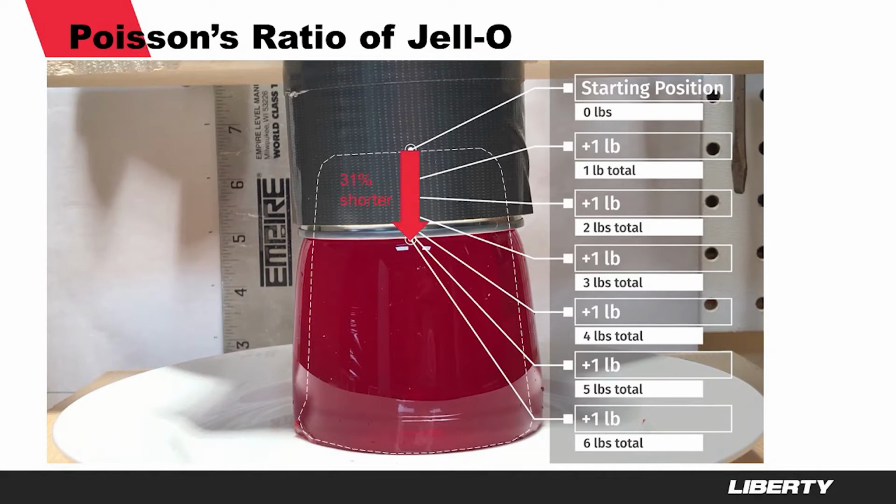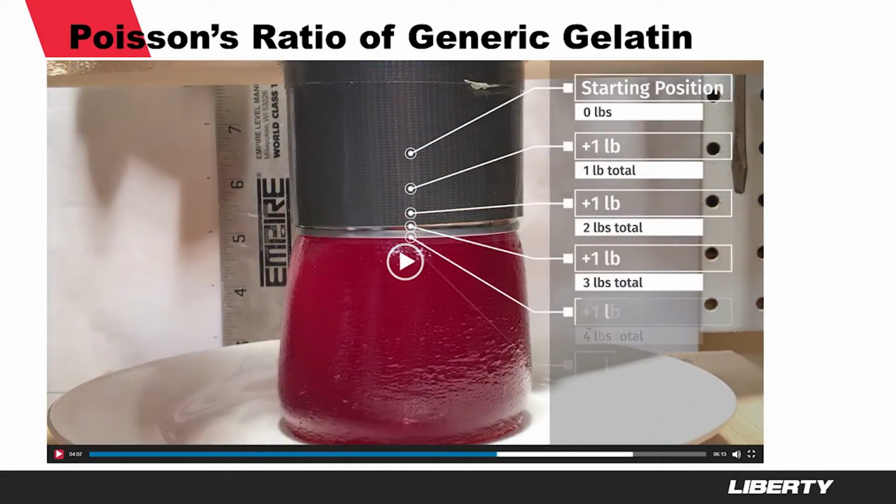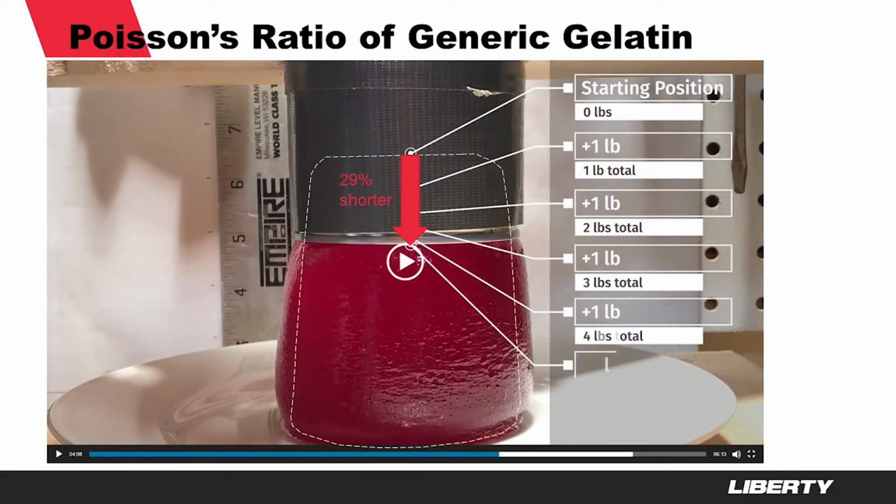While the shortening and bulging are somewhat nonlinear, on a large scale we see the following. Jello becomes 31% shorter while bulging about 14%. That's equivalent to a Poisson's ratio of about 0.43. And gelatin becomes about 29% shorter under a load of about 5 pounds, while it's bulging about 13%. That's a Poisson's ratio of 0.44.